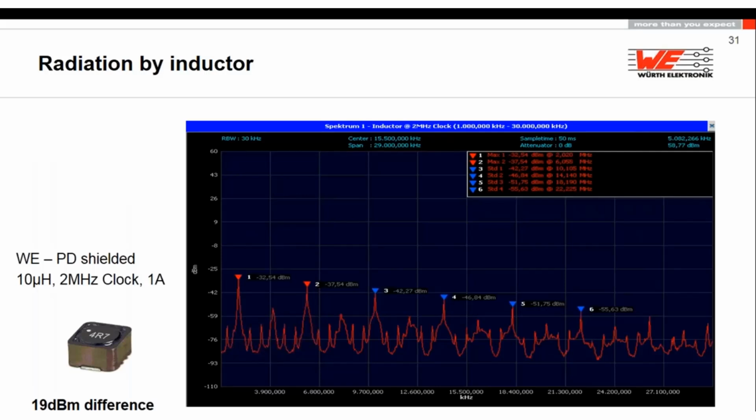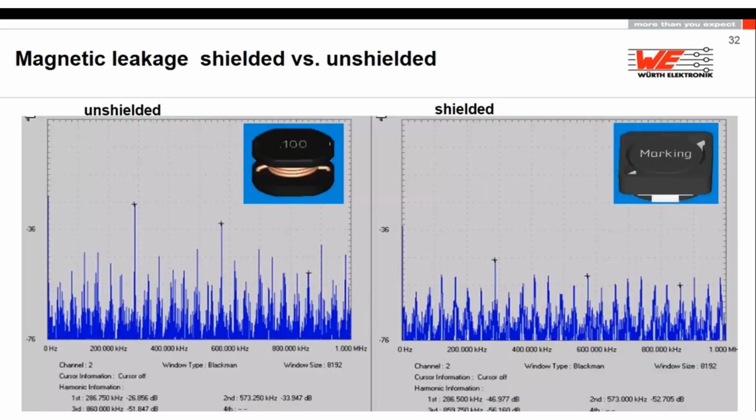It will happen that your peak on the conducted emission will drop almost 90 dB better. So just because of the shielding, it will not contaminate the system, and sometimes you can have a good solution for conducted emission. In radiated emission, I think I don't need to explain anything on this picture. In radiated emission, the inductor is the antenna which makes the noise. And if you put in the shielded version, it will be much happier.